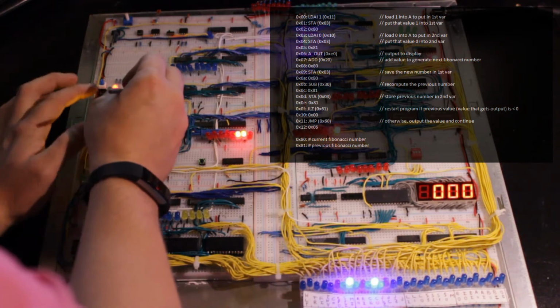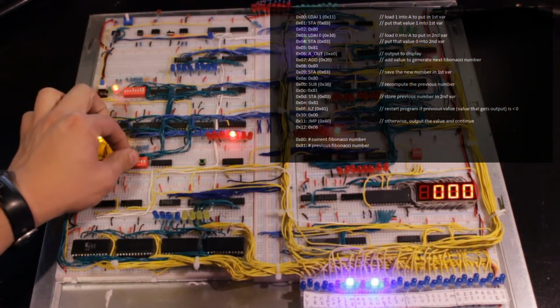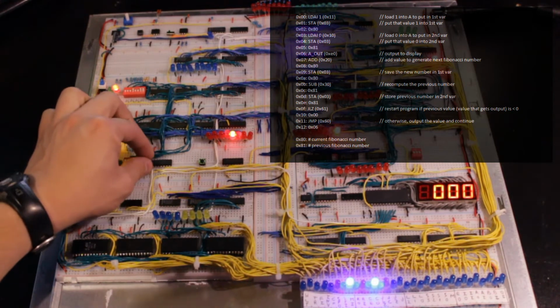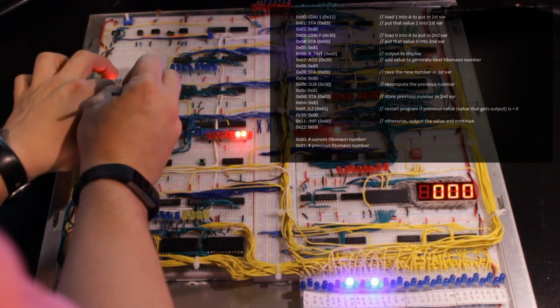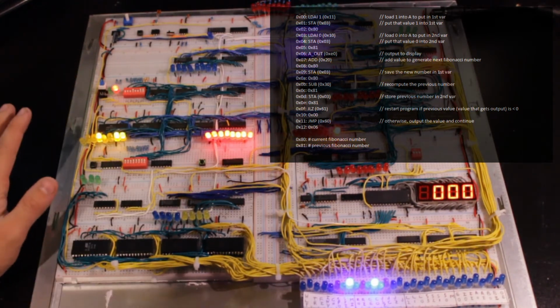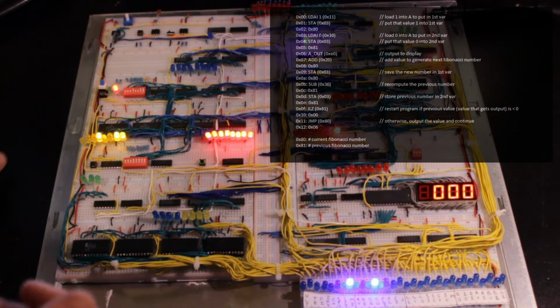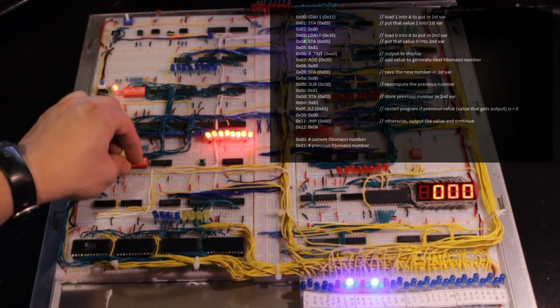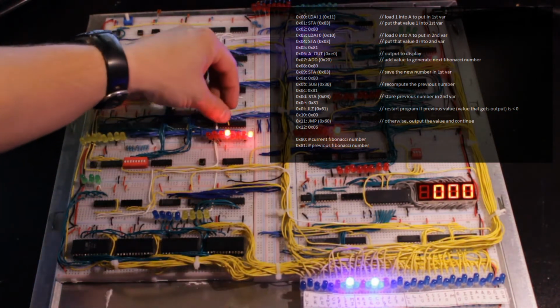And then for good measure, I'm going to add a halt instruction at the very end, just in case things go awry. We want to be prepared for that scenario. So here, the 6, and I'm just going to put a halt instruction there. So if we halt, we know that the program didn't run correctly. Now, before we are done programming this, we should go back through and check our instruction bytes against our reference sheet.